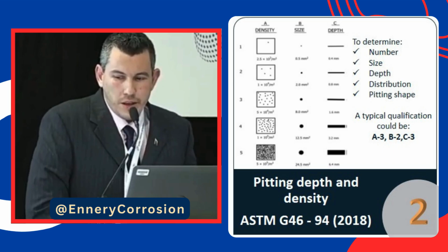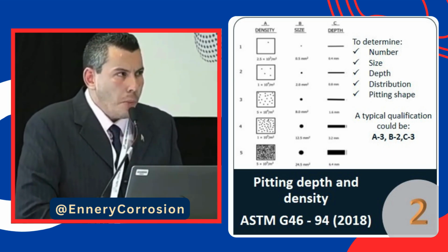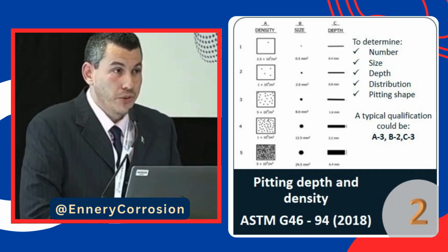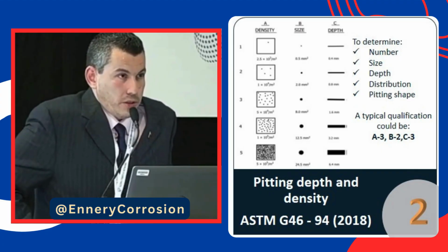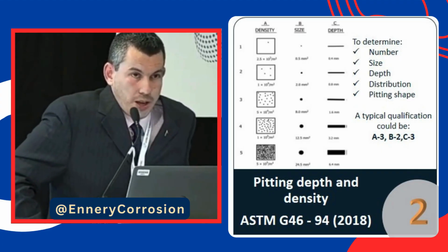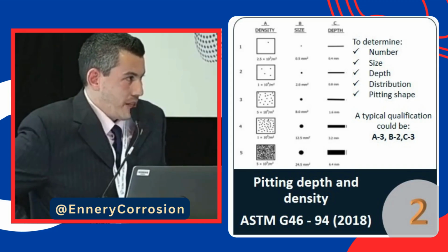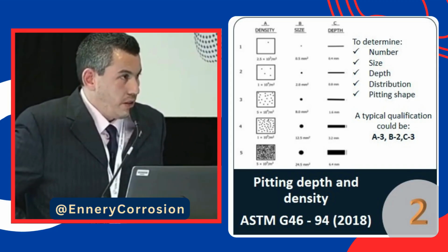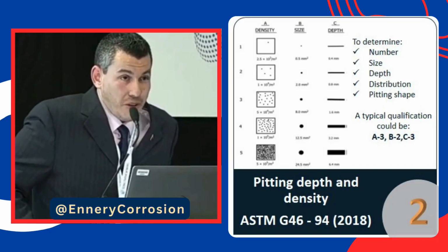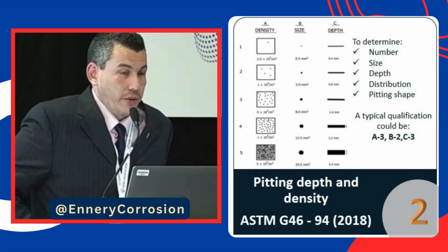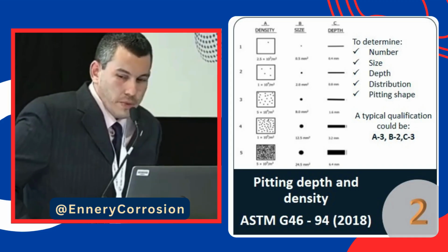Another information that we can get from the corrosion coupons, but unfortunately is not that commonly used, is that you can get information about your pitting rate. One of the biggest mistakes that we can make as operators is just to retrieve corrosion coupons, ask the lab, please, just tell me the corrosion rate based on mass loss. Because depending on the type of corrosion that we could have in our system, you could have pitting corrosion, and that's another headache. So you need to be aware of what kind of corrosion you have in your system.